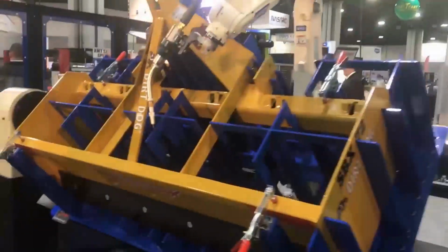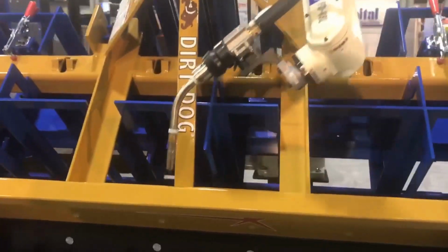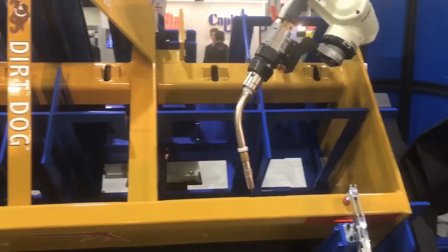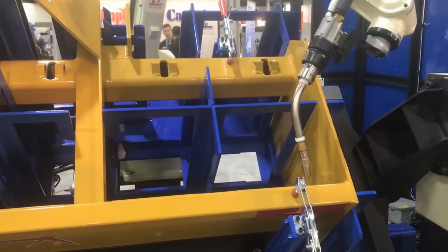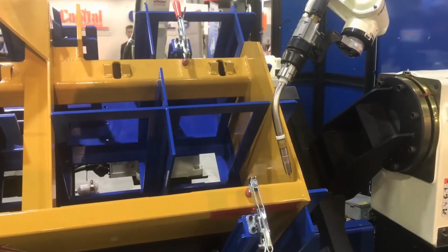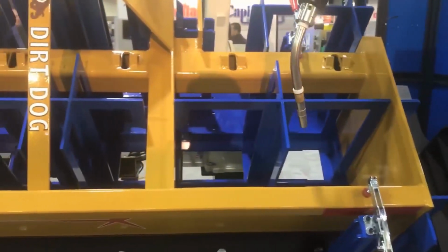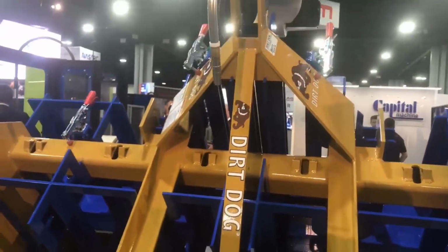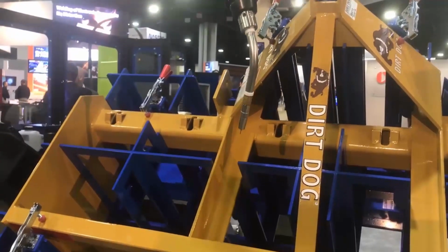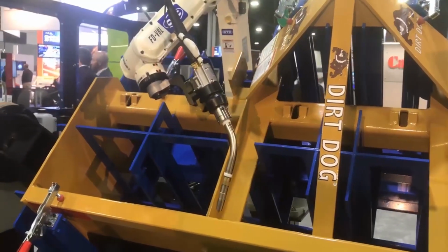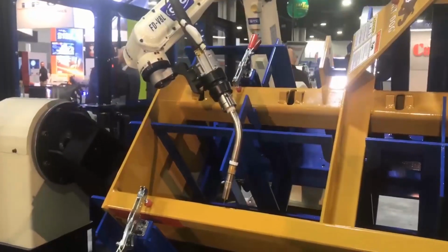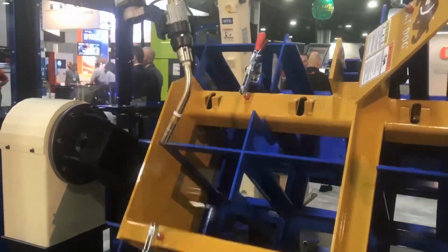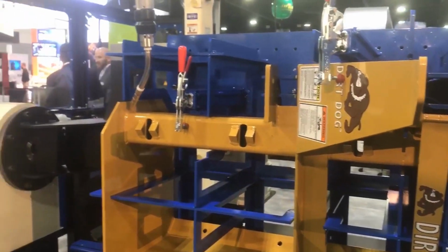This is an actual example of a very similar fixture to the one I just created for the same part, which we used at Fabtech 2018. You can see we have clamps and clamp towers included in this fixture. The part is on a rotary or a head and tail stock on a trunnion. Very rigid 3/8 material. Tack welded together.